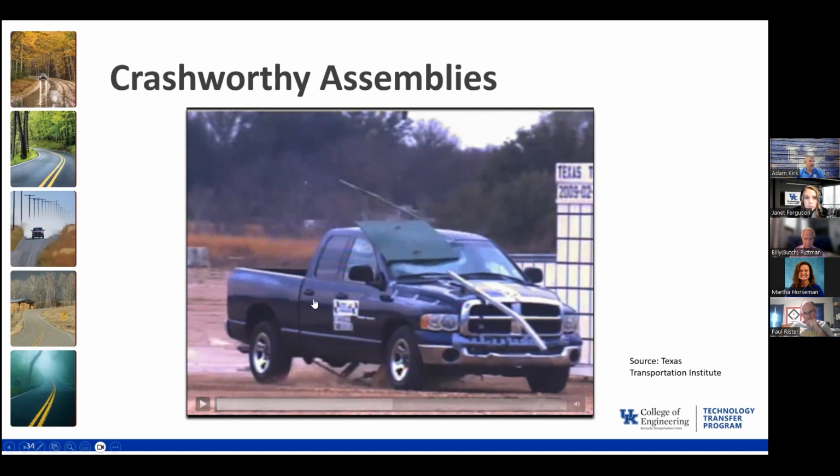So, you know, take your choice between both of those. If you're going to be departing the roadway, which would you rather hit? The one that breaks away and goes over your vehicle, or the one that's come in and impacts that windshield, you know, with the potential to even enter into the vehicle compartment? So two different impacts with a signpost, and just a small matter of what the tensile strength of that post is can make a huge difference in the ultimate severity.